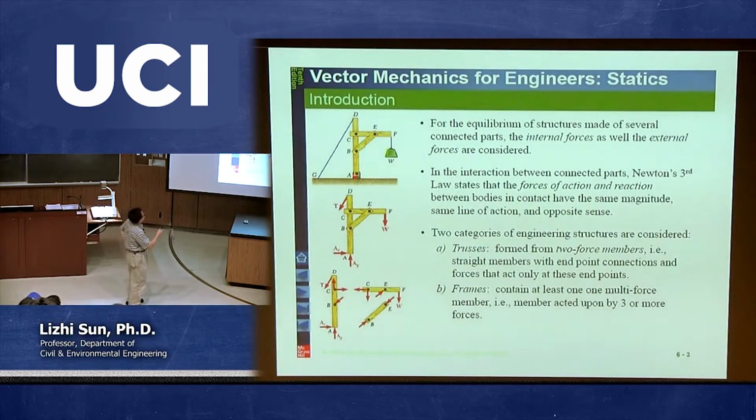For example, we see the rigid body like this. Okay, we put them all together, and then we have this kind of crate. So then we cut here. That is to isolate the connection from outside about this rigid body, and then correspondingly we give a force. Okay, so this is the force due to the self weight. That's easy. And this is the pin support. If this is a pin support, when we cut this one to isolate the rigid body from the outside world, then obviously we need to give 2 reactions.